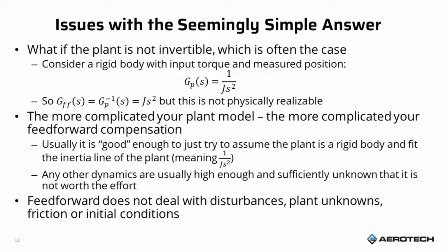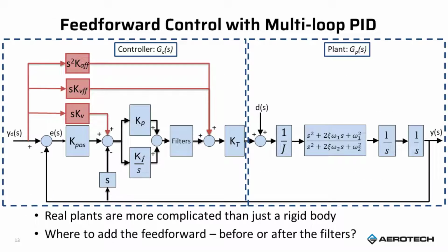Remember, using this feed-forward structure we're not going to be able to deal with the unknowns of the plant or the disturbances in the plant, but it will help us quite a bit in minimizing overshoot or creating a more optimal step response of the system.